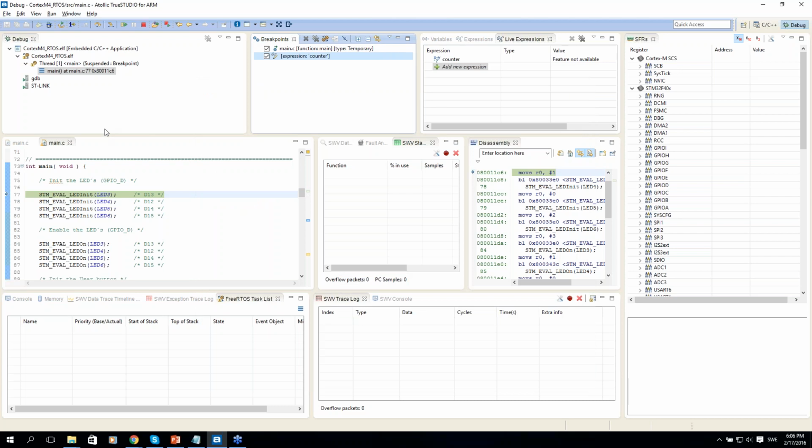So serial wire viewer tracing. What do we mean with that, and what are the capabilities that the debugger gains with this? Well, the serial wire viewer is an event-based type of tracing, which means that we can configure the microcontroller to emit trace data based on certain events that occur. So what do I mean with events? Well, let's look into the configuration of the trace.